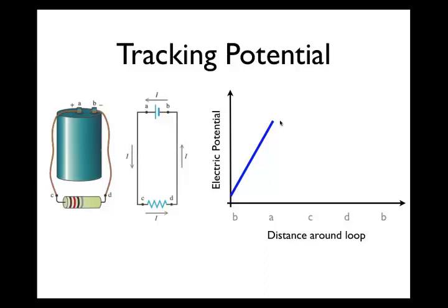as you process through the battery. If you go from A to C, you go through a conducting wire, and even though everything has some amount of resistance, the resistivities of materials like silver and copper and things that we tend to make wiring from is really low compared to the other things that we tend to make electrical resistors from, such as carbon.